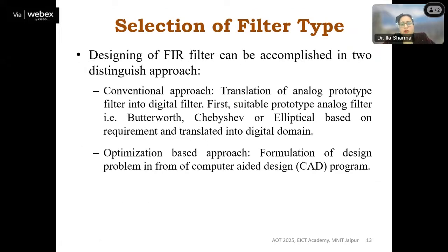So till now, how these FIR filters are being designed, there are two distinguished approaches. The conventional one is translation of the analog filter to the digital one, where a suitable prototype analog filter, that is any Butterworth, Chebyshev or other approximation, is taken. Have you heard about this Butterworth filter, Chebyshev filter? These approximations have very standard transfer functions.